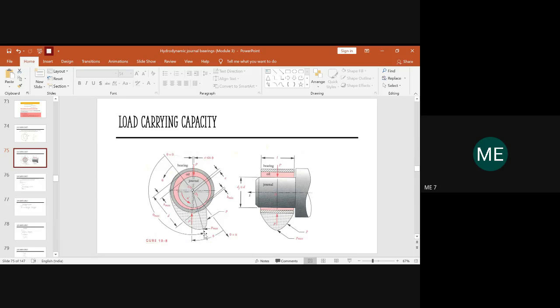So this angle, from the reference line till here, will be theta max, which means in this area the pressure will be the maximum. So even you have phi, where the pressure will be minimum. This is the direction in which the oil will be injected. Sometimes the oil inlet could be inclined at some angle based on the reference you are taking. So even the angle of inclination of the oil inlet will also be given.